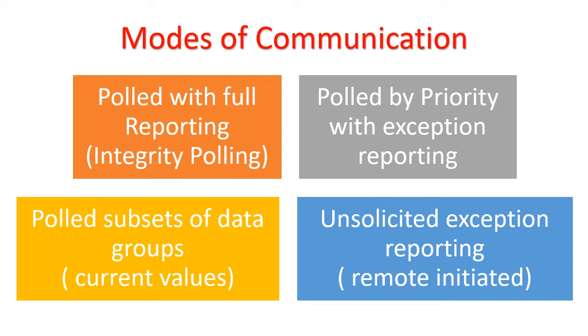There can be polling with full reporting, polling with priority, polling with subsets of data, and there is also an option of unsolicited response or unsolicited exception reporting, which means that the master and remote now have multiple options of communication.